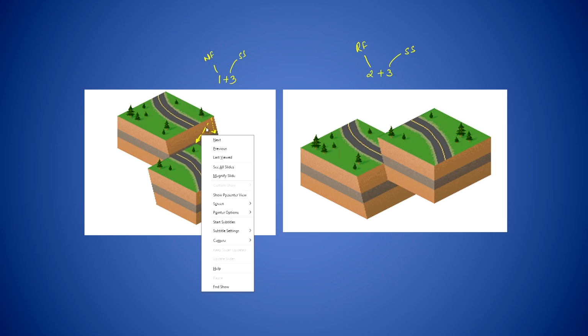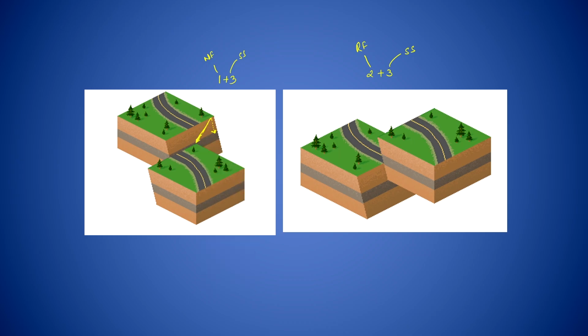So you have these two sets of displacement, and in this case the block has moved up, as well as the block has moved in this direction. So this is reverse, as we have discussed here. This is reverse plus strike slip and this is normal plus strike slip. And such faulting or deformation we term as oblique slip faults.